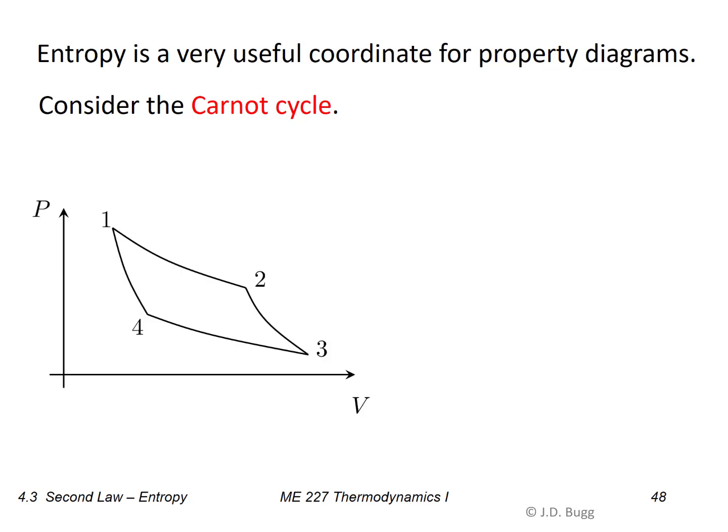So this is how we've seen a Carnot cycle so far, on PV coordinates. So just to review, this is an isothermal process. This is an adiabatic process, then another isothermal process, and finally another adiabatic process. So 2 isothermal processes and 2 adiabatic processes. Now remember, for a Carnot cycle, in addition to that, all 4 of these processes are reversible.